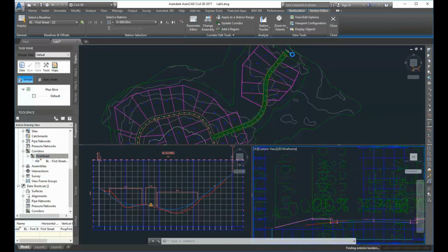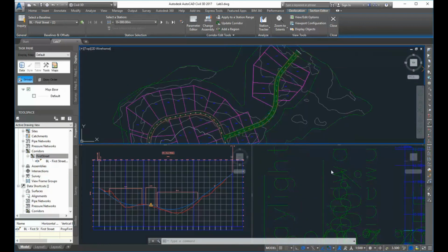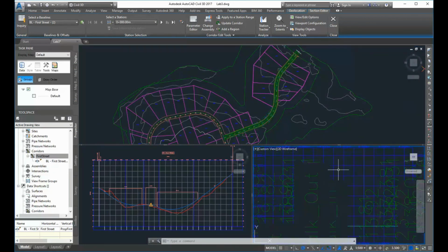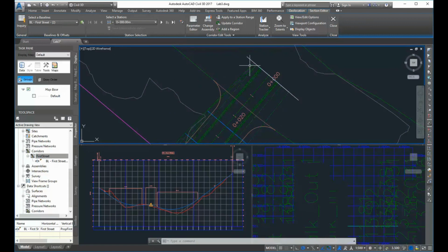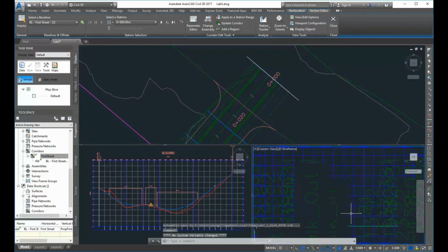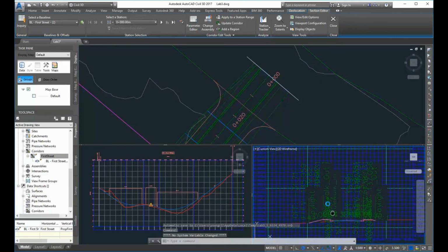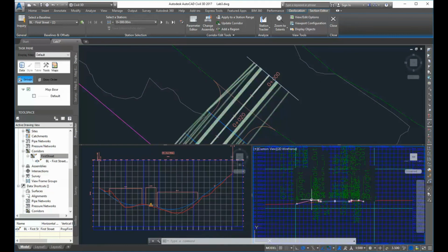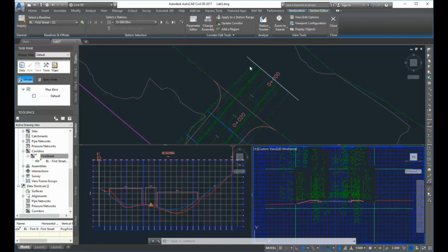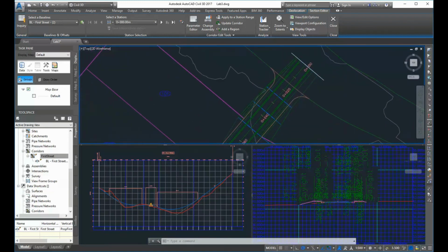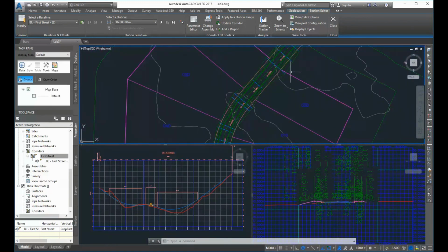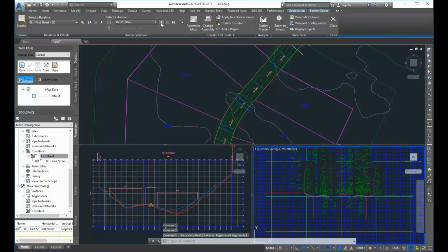And so up in here, oops, sorry, I zoomed to the wrong place. If I make each one active, right? The back of these outer green lines is where those are matching, right? So that's how far out from the back of the sidewalk it needs to go until it can match, right? So these become important if we want to know how much impact our road is having, right? How much, so you can see in some places it gets pretty far out. So if I were to hit this kind of play, it'll go in even sort of 25 meter stations.